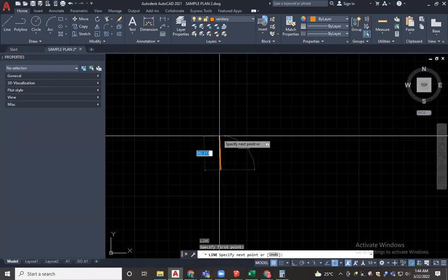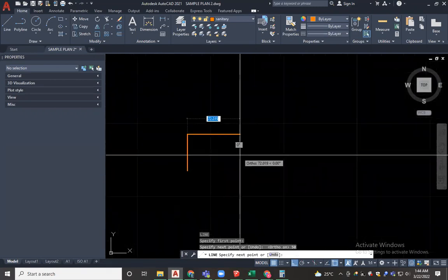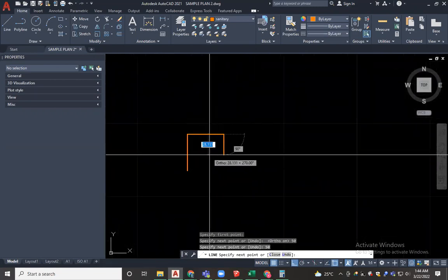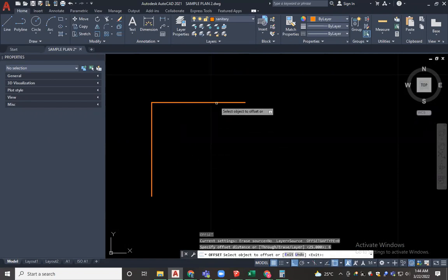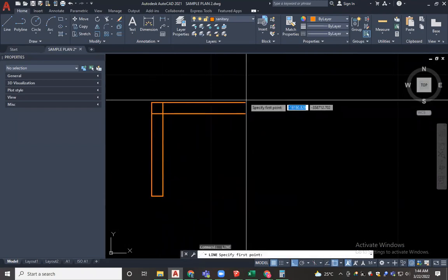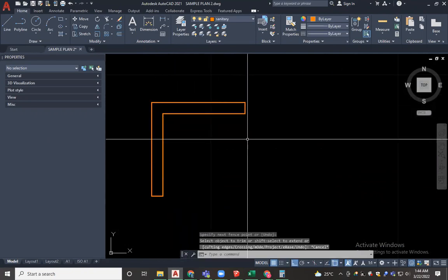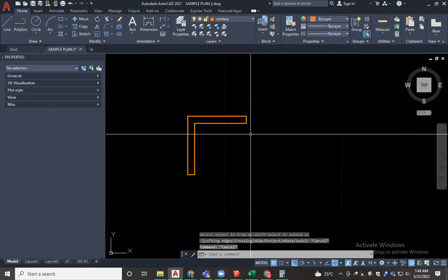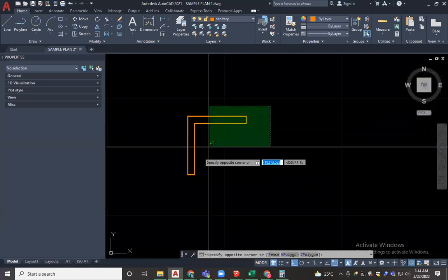Say the angle bar here, 2-inch, that is 50 by 50. So thickness is 1/4, so that is 6 mm. Let's say ganyan yung ating cross section. So para makuha natin surface area, perimeter nito times yung length times 6 meter.